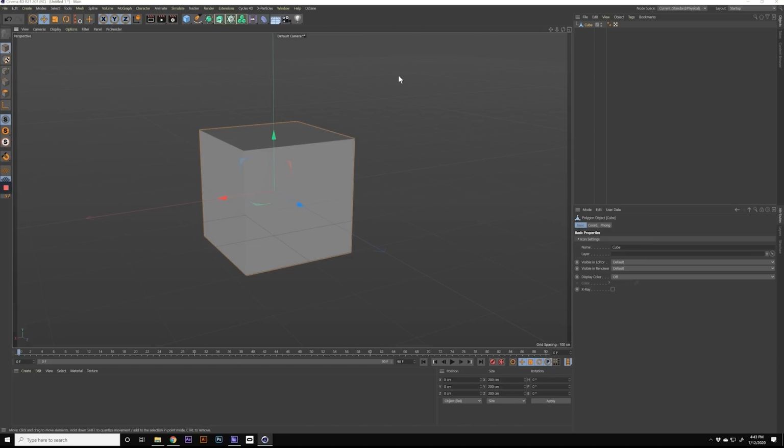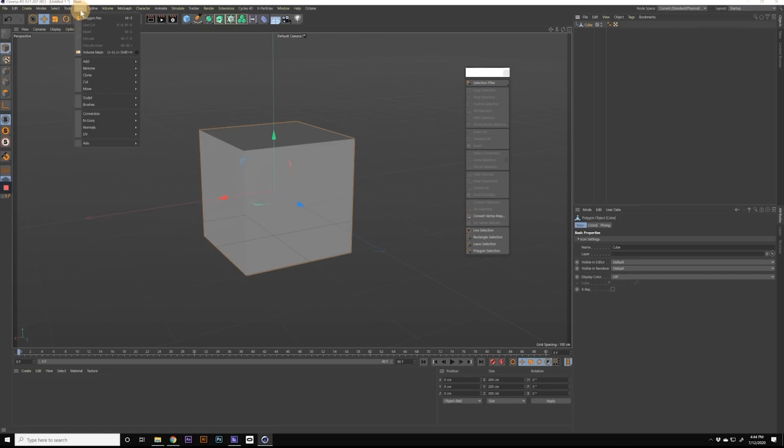And so we'll press C, and now the cube is editable. If you're not familiar with a lot of the modeling keyboard shortcuts, I'll usually come over to Select and hold this bar right here to undock that menu so you have it on your right hand side, and also your mesh tools here. So that bar, there you go. So now these are most of the tools that we'll use to create the hand.